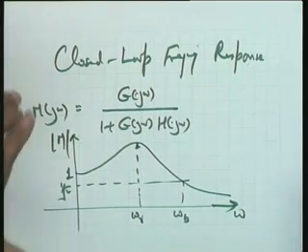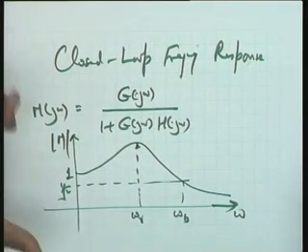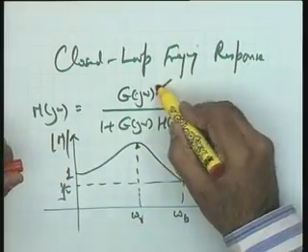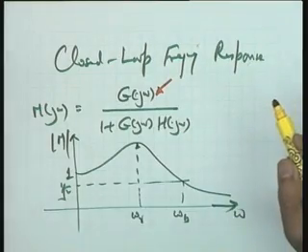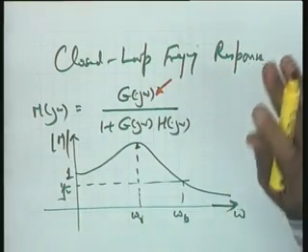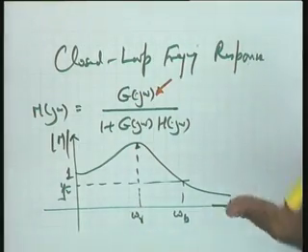You may be feeling as if there is no need for any repetition of this. I am repeating this because my next point is how to obtain these values, the analysis problem. For phase margin and gain margin, you immediately make a sketch, the Bode plot sketch, and from there give me the values of phase margin and gain margin. Now my question to you is: given the open loop frequency response data, either the experiment has been conducted on the open loop system or the open loop transfer function is available to you, give me the indices Mr, omega r and omega b for that particular system. How to get those values is the question.